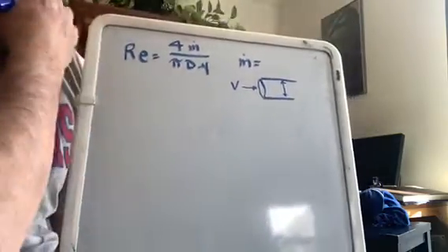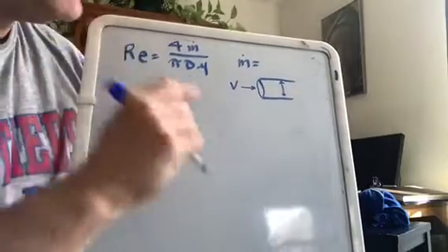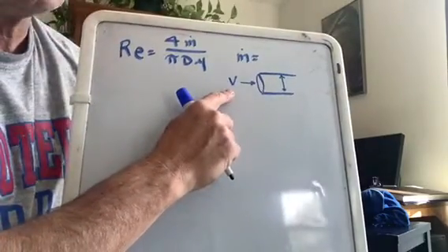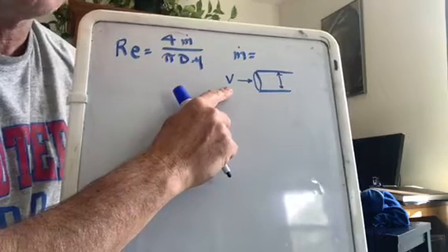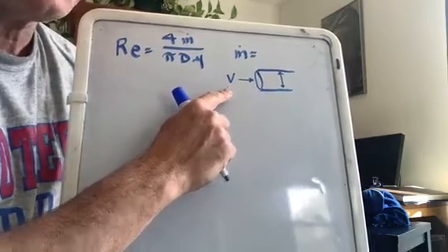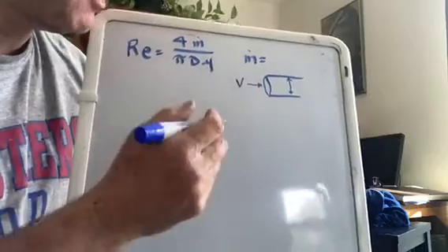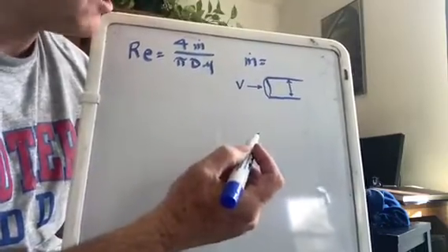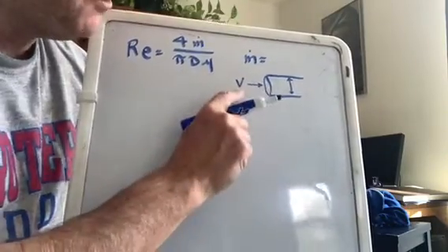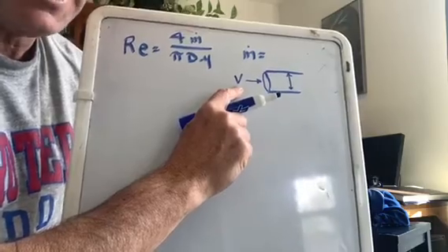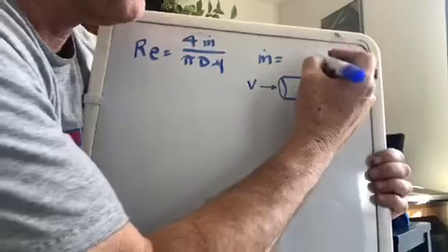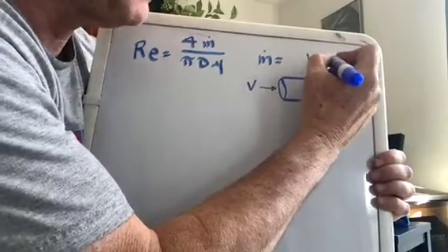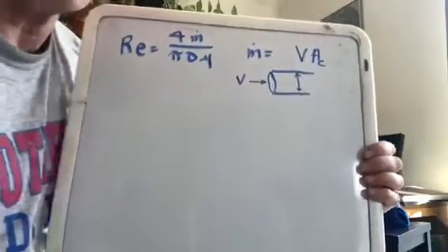The other form comes from the fact that in many scenarios, we actually figure out the Reynolds number by thinking about the average speed of a fluid. So that can easily be incorporated into this. So a quick reminder how that works. If you have a fluid with speed V, average V, going through a pipe with cross-sectional area A, the volume flow rate can be gotten by doing that speed times the cross-sectional area.